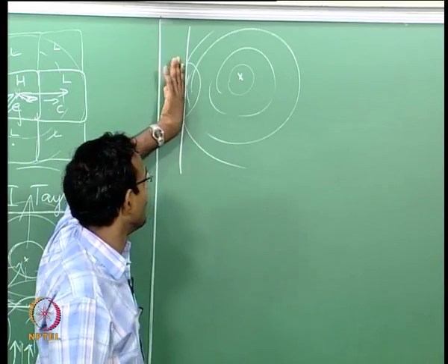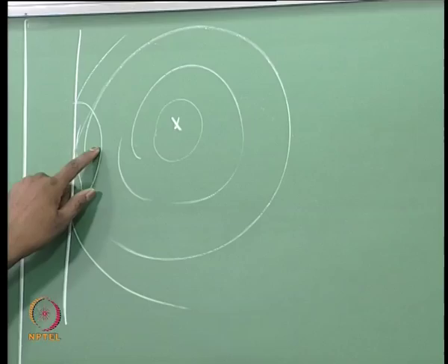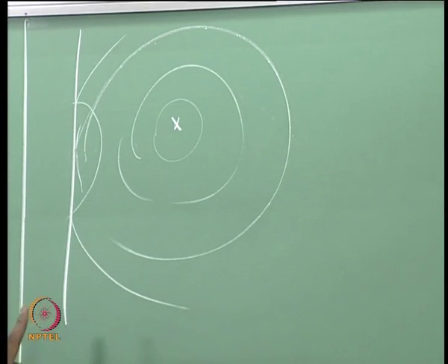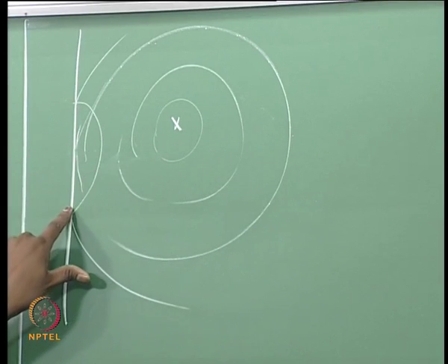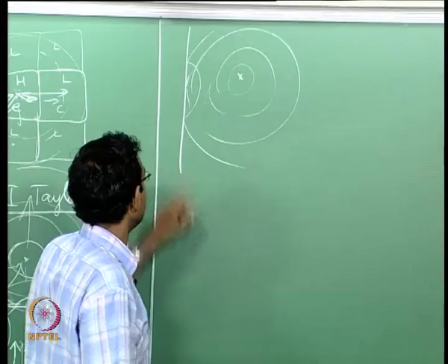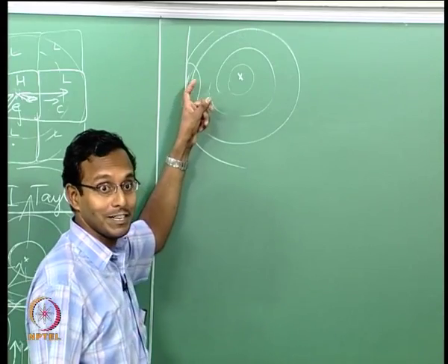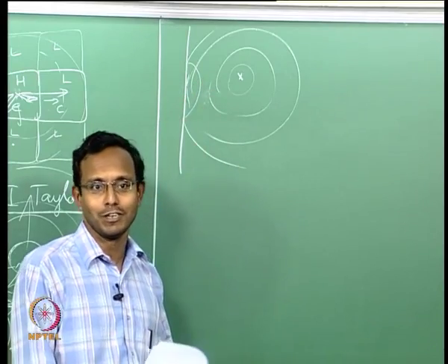Okay. This is a new wave because this is not going to have the same Mach number as this wave. Why? This is not experiencing the same flow field as this one, this is experiencing 0 moving flow, while here the fluid is already going this way and this is fighting against that. So the Mach number etc. will be different here. Okay. This is going through a gas that is already processed by the previous gas. So it is a new shock, think of it that way, it is easy to think about.